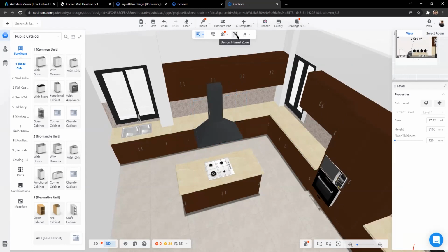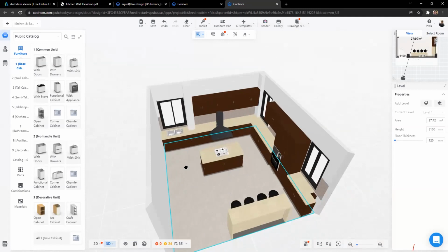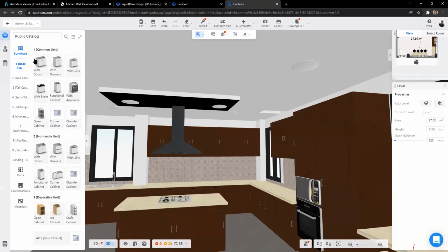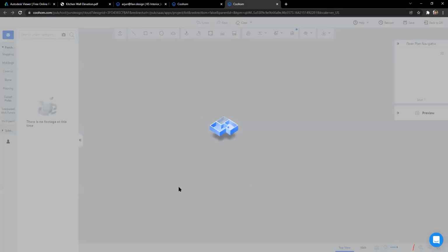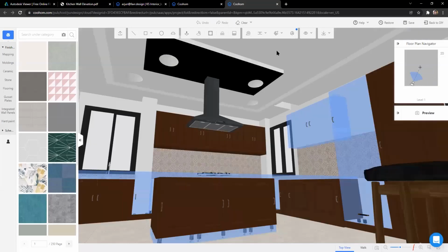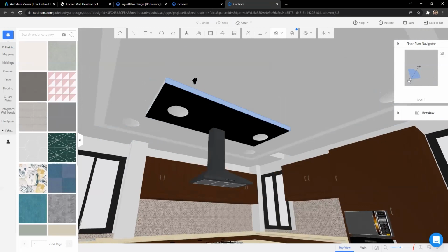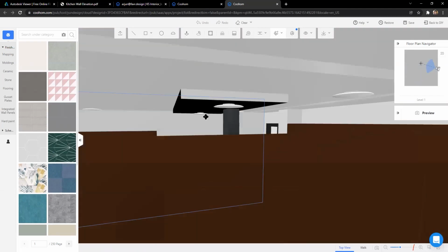And the internal zone, which we've already discussed, and then the generation, which we've already done on this thing. And then we'll move on to renders. Okay, we have to apply a texture here. So I'm gonna go to construction. Have to pick the texture that I've applied here and then paint over on the edges so that it won't look awkward in the render.